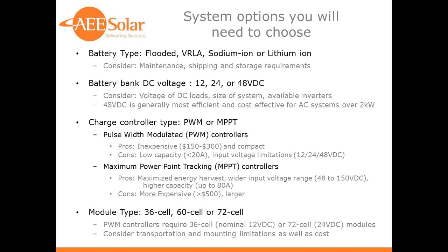But certainly we're paying attention to all these technologies. We're testing a few of them, such as Aquion's sodium ion batteries, and we're certainly working with Tesla to develop their battery technology too. So there will be other forms of technology, but right now today we're still really dealing with lead acid. But there are maintenance considerations, and it might be a choice to use a sealed battery rather than a flooded battery if there isn't a competent person to do maintenance on the site.